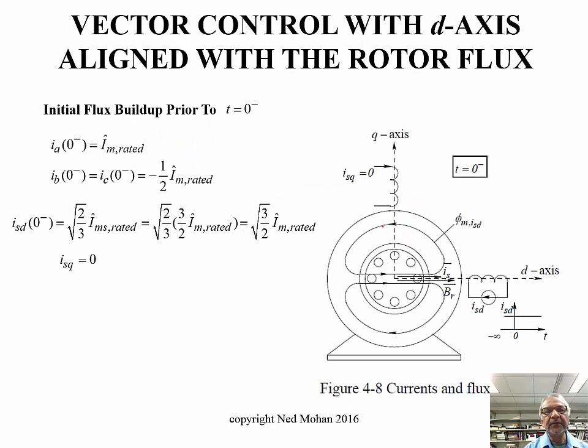All right. So in vector control, let's say that we start by first establishing the flux in the machine. So how do we do that? Initially, everything was zero, nothing, no currents, no fluxes, okay? But slowly we build currents in phases A, B, and C such that along the A-axis, which is also, let's call it D-axis over here, this flux density distribution peaks.